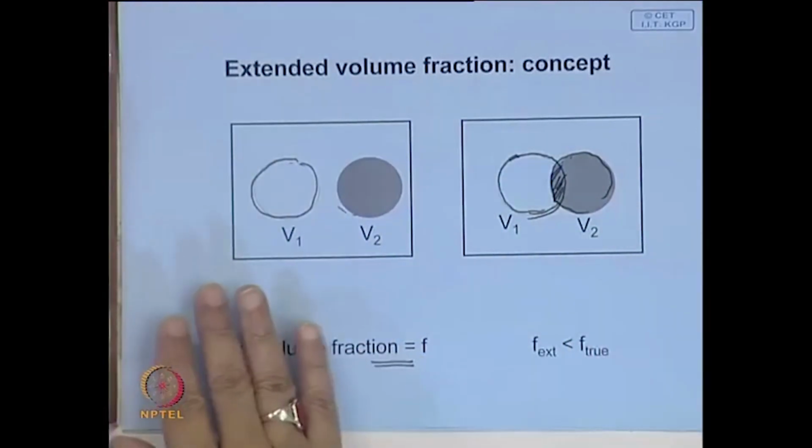And we shall look at how, with this concept, it is possible to derive a definite expression for fraction transformed, say for a pearlitic transformation or any diffusion controlled transformation. This in fact will be even applicable to precipitation kind of transformation. The only difference is that in the precipitation process in a supersaturated solution, the volume fraction of precipitate is very low, very small. So, the question of impingement does not come there, because the volume fraction will be so low that impingement may not be necessary.